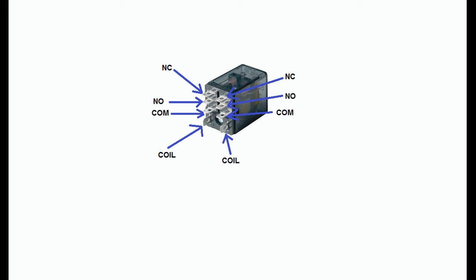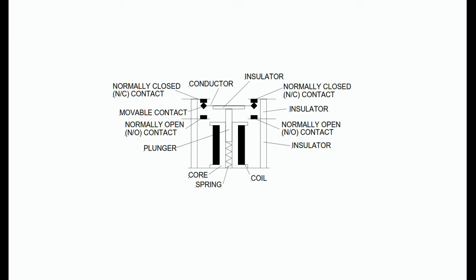When the electromagnet is energized by passing an electric current through the coil, the magnetic field pulls the plunger into the core, which pulls the movable contacts downward. Two fixed pairs of contacts are mounted to the relay frame on electrical insulators so that when the coil is de-energized and the movable contacts are not being pulled toward the core, they physically touch the upper fixed pair of contacts and, when being pulled toward the coil, touch the lower pair of fixed contacts.